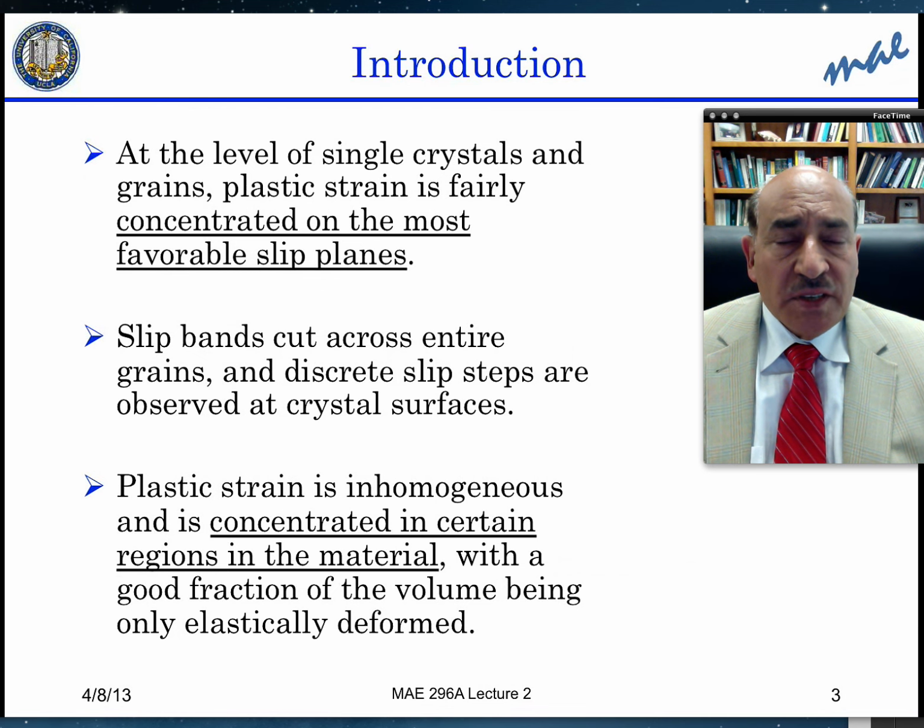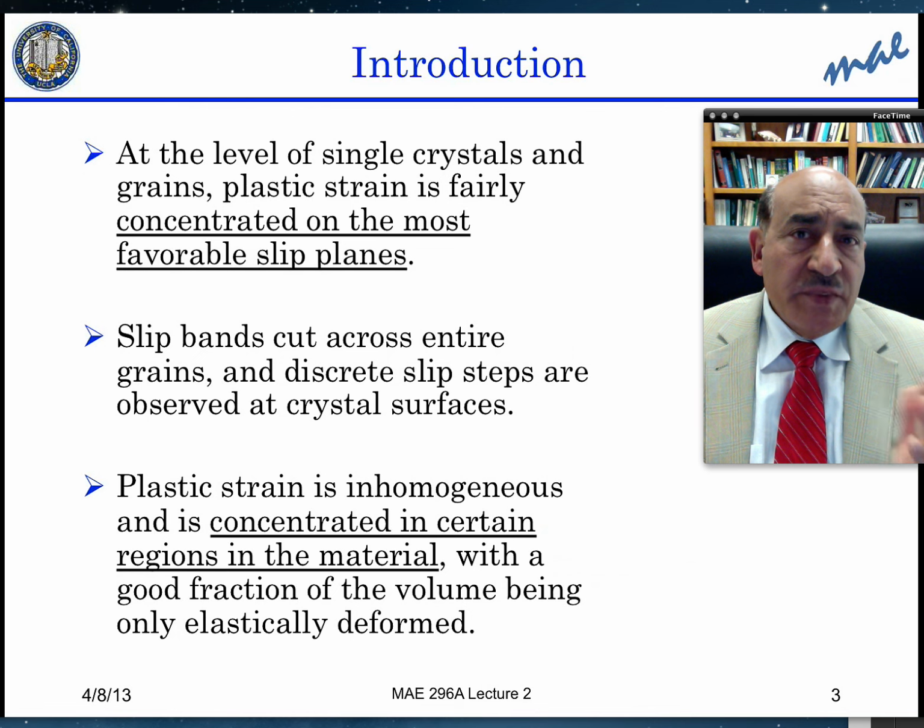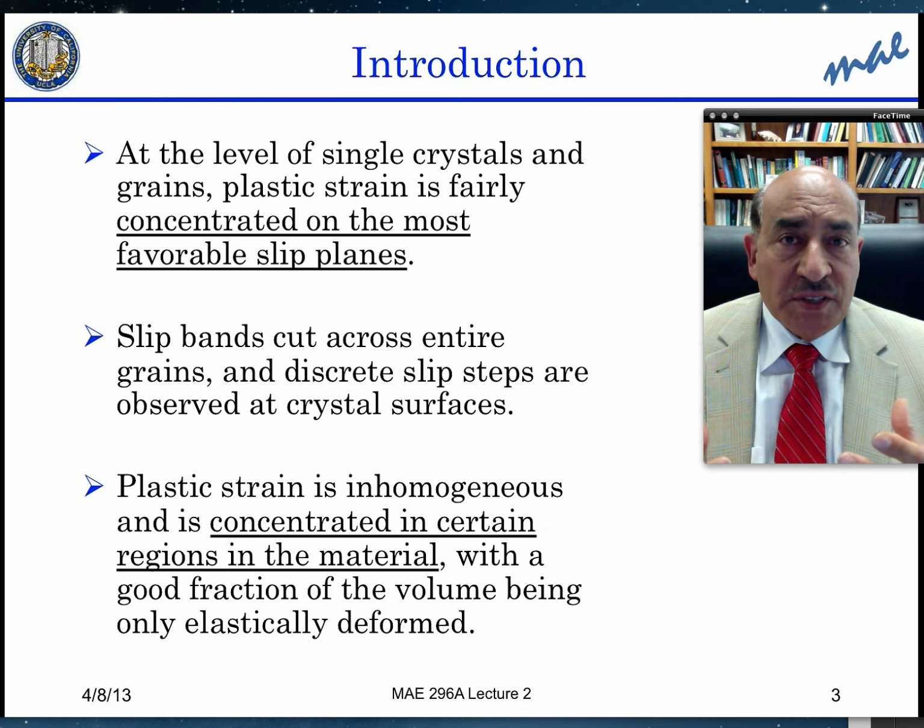Otherwise, we will just look at crystals as material that will deform, and the deformation usually leads to concentration of the plastic deformation mode in a small volume of the material, and leads to failure by an instability type of situation, like a necking instability, which we'll consider in the next lecture.